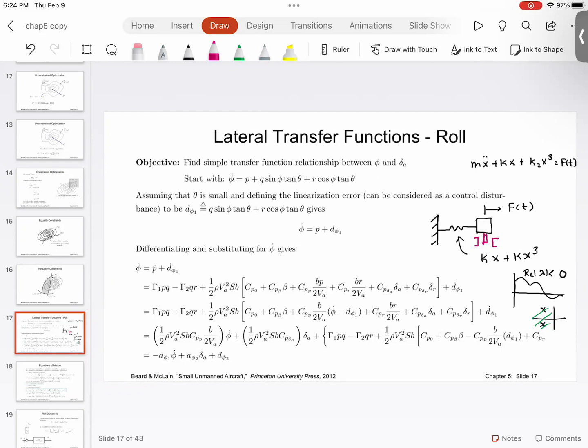Everyone understood this? Think about it like a handle. If you adjust the strength of the electromagnet, you will control the motion of the centerpiece. And that strength can be very easily varied using the amplitude of the current and the frequency. So you can simply use a PWM to control the intensity of the magnetic field. It will be just a simple PWM controller, and an Arduino can do that. Now you want to program the Arduino sketch to implement a controller algorithm.